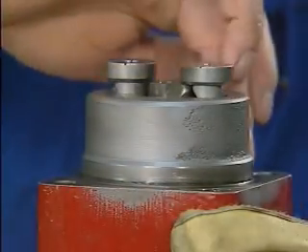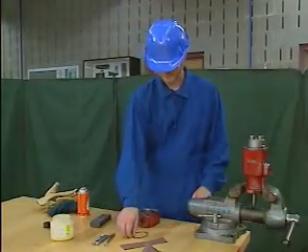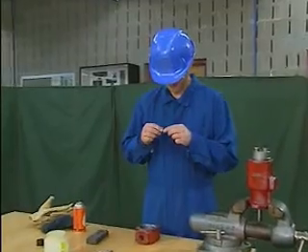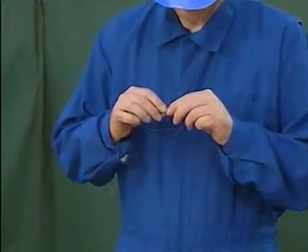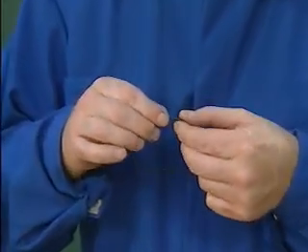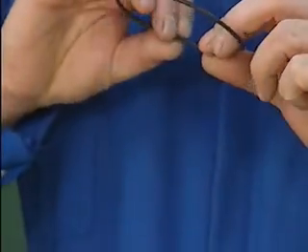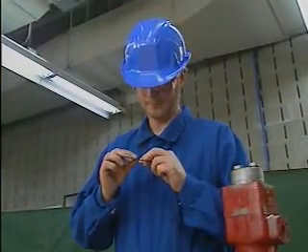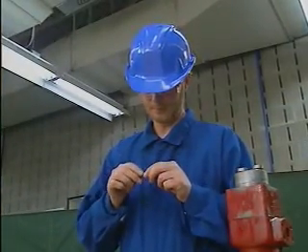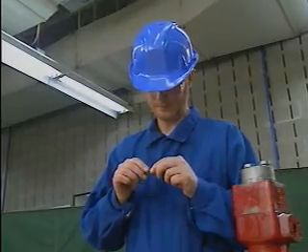The sealing surfaces are in good condition, so the mechanic then checks the O-ring selected for this application to make sure that it's free of cuts or other damage. If the O-ring is damaged, it may not seal properly and should be replaced. Even slight damage or irregularities in an O-ring could prevent it from sealing properly, or could cause the O-ring to fail prematurely.